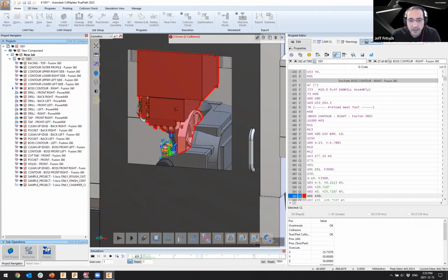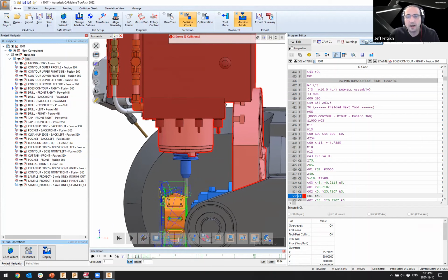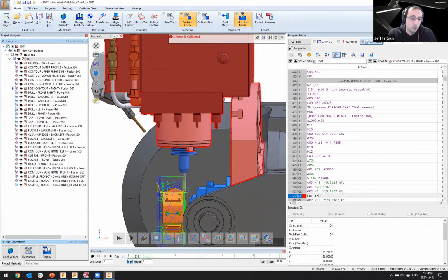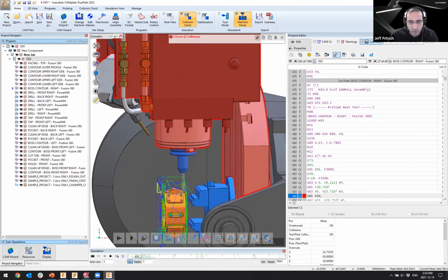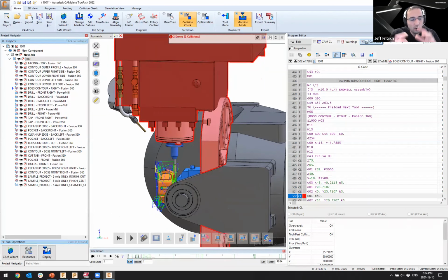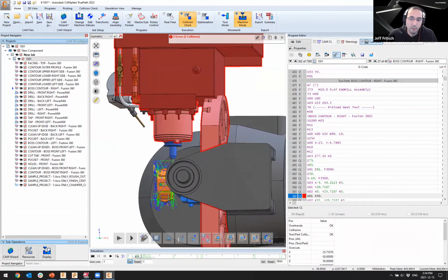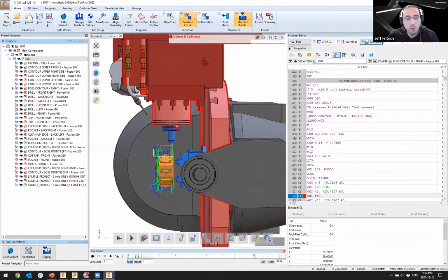Looking now at the interaction between the spindle and the table, we can clearly see that even though the toolpath, the way the tool is moving around the part, is absolutely proper, it definitely does not interfere with the vise whatsoever. It clears the material appropriately, very similar to what we saw in the very first video. Now, all the elements surrounding the toolpath, so the spindle, the table, how the machine moves, are interfering with the actual ability to make this part properly. So looking at those elements, what options do we have available to fix them?